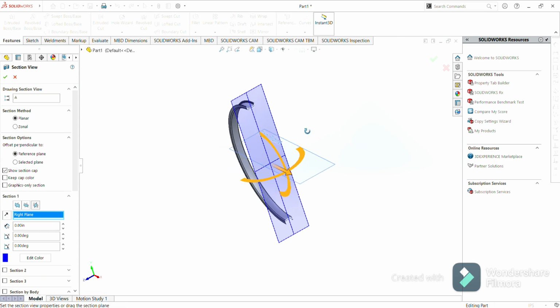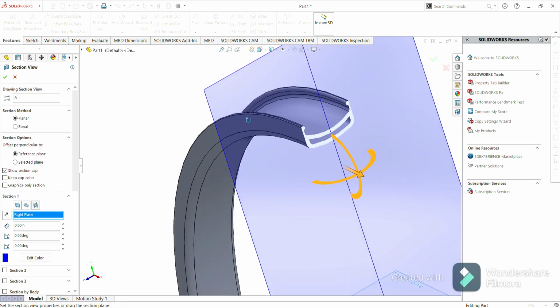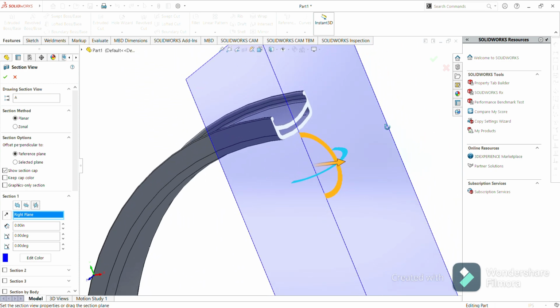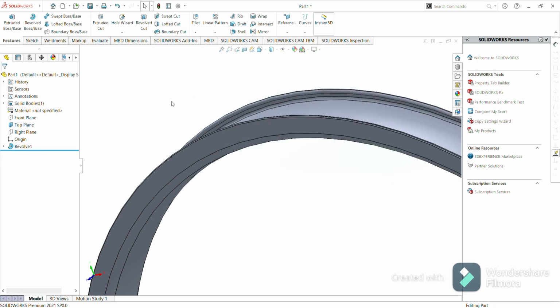Here you can see this is our rim. The inside surface is created as a hole for pins. We create some pins for this, so cut this and make it normal.